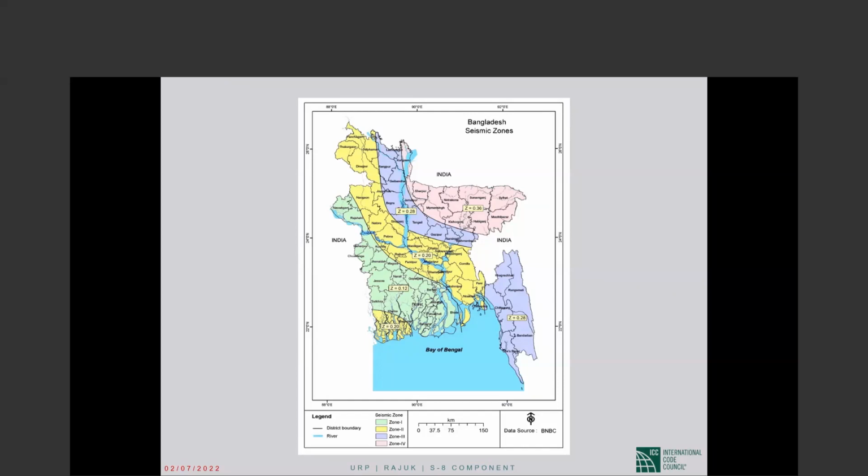The repair itself is expensive and it is disruptive. So the building will probably not be possible to occupy while the repair is going on. So an existing building with a weak story is a significant problem, and there is no one answer that anyone can give you. It will depend on the building, what you can do, or what would be a more effective solution.